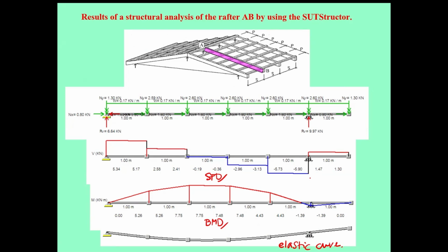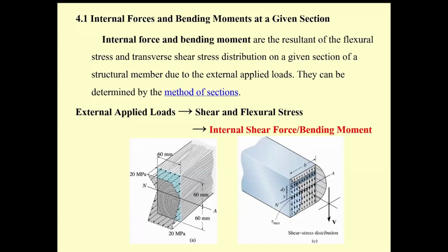This is going to be the maximum shear force, and you also use the maximum bending moment, because you take this point to take the impact, and then you decide based on that. You get the section, then you check for the shear, you check for the deflection. That's going to be the whole process.